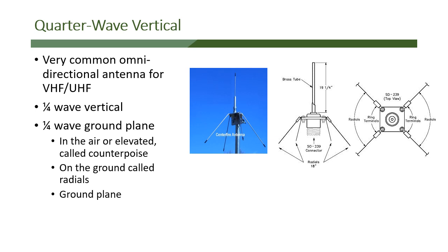Their function is the other half of the antenna. So that's what we're basically doing: the vertical is one side of the antenna and the ground plane is the other side of the antenna. We use a certain number of wires in the ground plane, more than the vertical, because we're creating a path to help return the energy back to the coax and down to the transmitter. Remember, we're sending energy out, and then of course we're getting energy back on the return side.